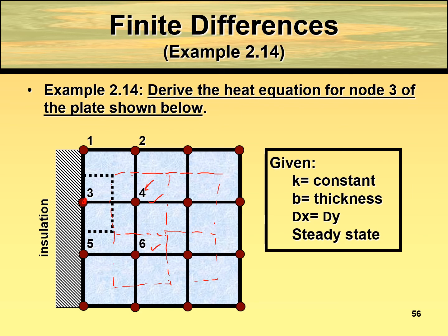Now what about node number 3? Node number 3 is not a full node. Node number 3 has got only half a node. So you can't use the equation directly, but because you have insulation and node number 3 is half a node, what you can do is use a mirroring technique. So imagine you put a mirror here and you reflect to this side, and now you get a full node. Now because you have node 1 here, node 3, because of the mirroring technique, this is mirrored here.